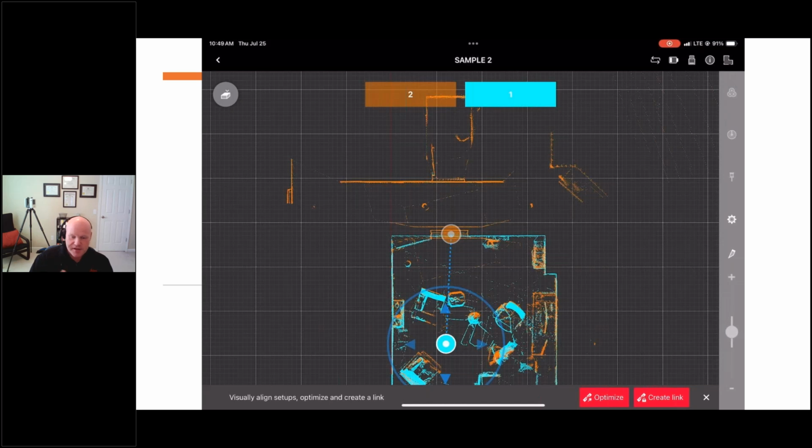a calculation as optimize. And if you click this gear icon, there's a level of detail setting that, if you're using a more capable tablet, something like an iPad Pro or a high-end Android, you can run level of detail high, and it will bring more of the data in for a preview and use more of that data for your cloud to cloud. But the quick link just does a closest neighbor calculation, and that's all it really needs, because the Viz is so accurate on its own usually that quick link is reliable, ready to go. The next approach that you can use is